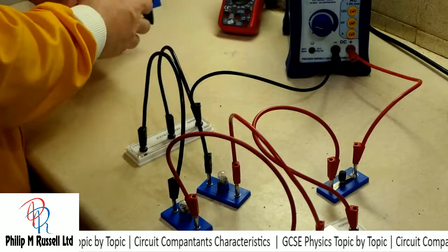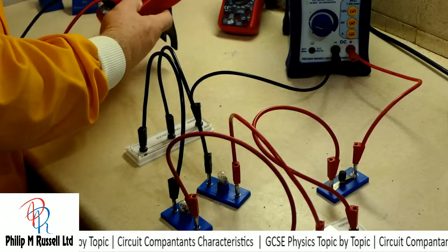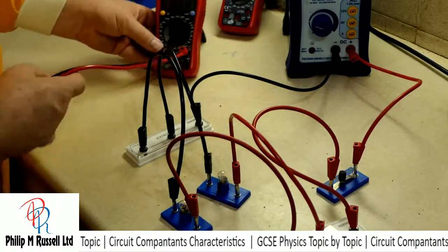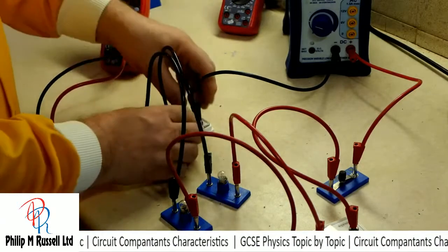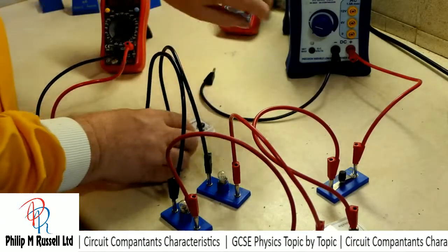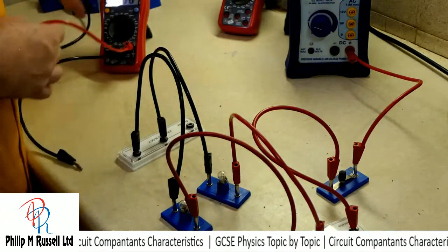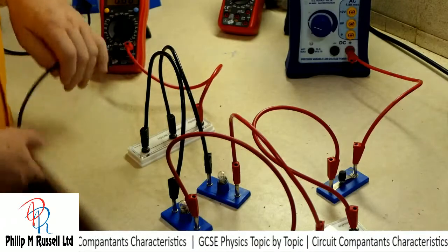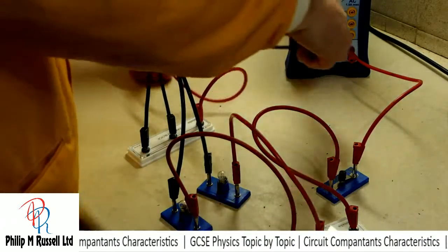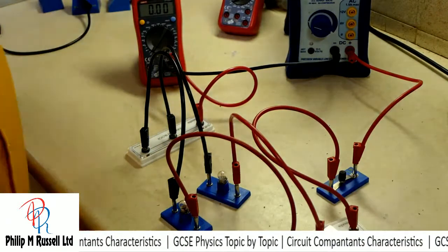Now, since my ammeter's not working terribly well, I'm going to turn my voltmeter into an ammeter, and I'm going to replace the first wire with the ammeter. And we'll see what the amps travelling along are going to be.